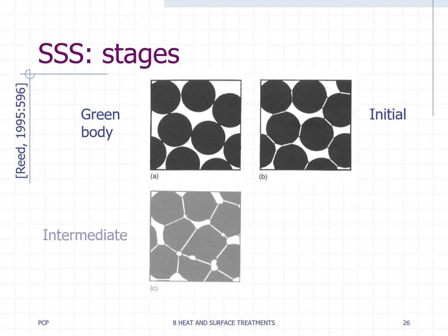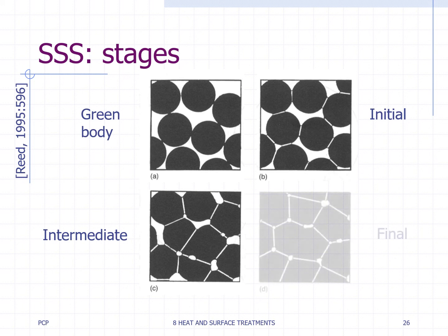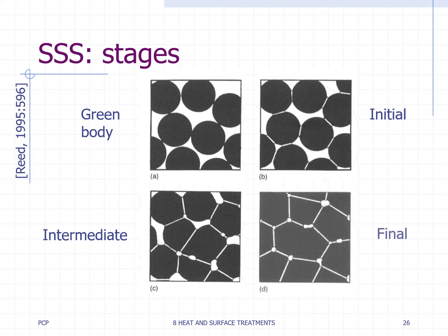Intermediate: shrinkage of open pores intersecting grain boundaries. Mean porosity decreases significantly. Slow grain growth. Final: closed pores containing kiln gas form when density is about 90%. Closed pores intersect grain boundaries. Pores shrink to a limited size or disappear.